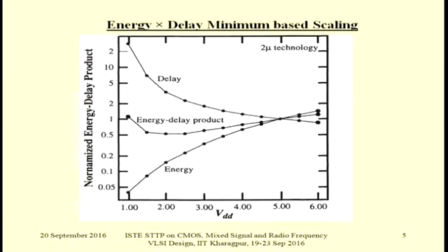Remember that in low power design, we have to maintain a basic throughput and at the same time afford only limited power. So if you optimize the energy delay product, as we have done in the expression, the power supply should be equal to 3 times Vt. So that means we have to take some optimum value here.